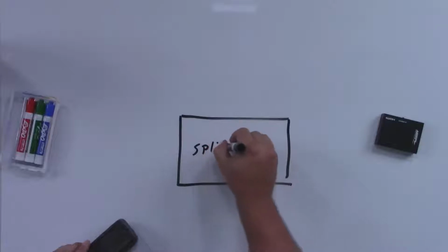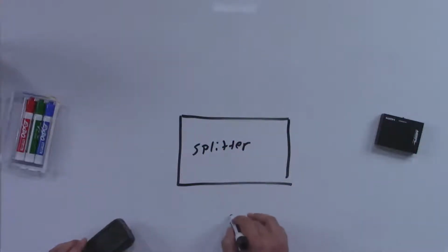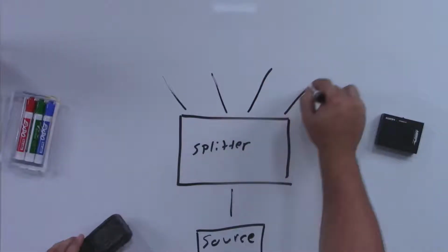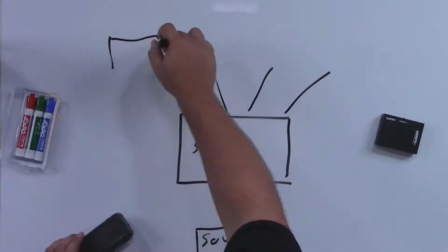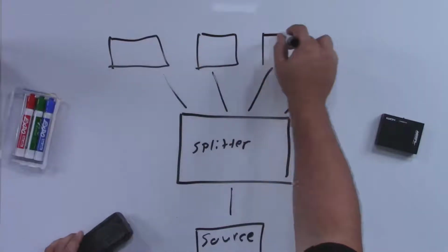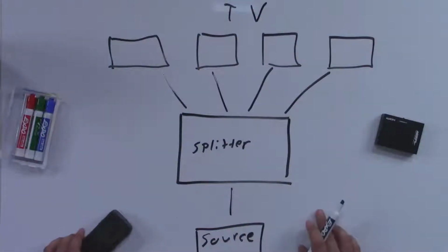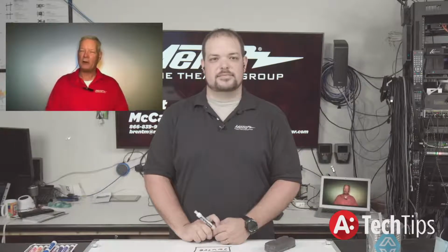Do you need a 4x4, an 8x8? Do you need to go beyond that? Do you need to split out audio? Do you need to track audio on the input? There are a lot of things to consider with advanced HDMI distribution. One of the nice things when you call us is that both Adam and I have whiteboards by our desks. We'll put you on speakerphone and lay these things out in front of us so we have an idea what's going on, and we can help get the system laid out correctly and efficiently so you're not standing around trying to figure out what you're doing. The matrix is without question the center point of your distribution.